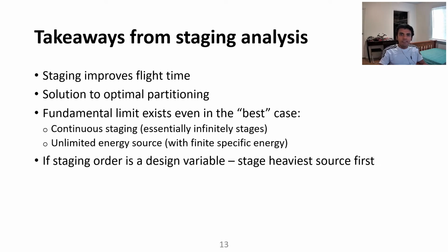Let me quickly summarize the takeaways from the staging analysis before going into experimental validation. We showed that using an energy source in stages improves flight time. We considered the optimal partitioning problem and derived the solution in the form of simultaneous nonlinear equations. We then showed that even if we continuously stage the energy source and use an unlimited amount of energy source, we can still only get a flight time which is finite. Lastly, we proved that if one were to maximize flight time based on the staging order, then the heaviest energy source should be staged first.